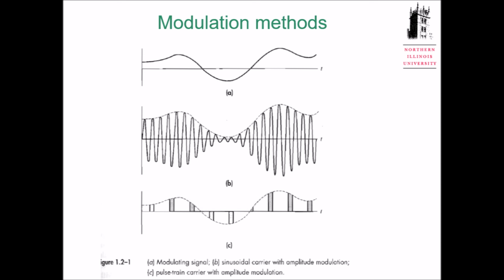This one, now we have multiple impulse signals. So we call this one pulse modulation. Here we change the pulse amplitude, so this one is PAM. Later we talk about PWM, so the width of your pulse can be wider or narrow. We also have PPM. Position of your pulse can be towards the forward or towards the end of this period. So we have PAM, PWM, PPM.